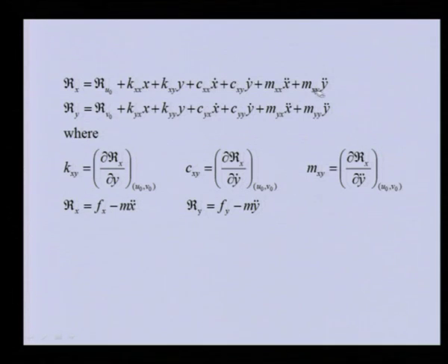and these are the terms basically for the Reynolds equation, because we are not considering the fluid inertia. So, these terms are generally present when we have very high velocity of the rotors. So, these are called mass coefficients. So, this stiffness, damping and mass coefficient.